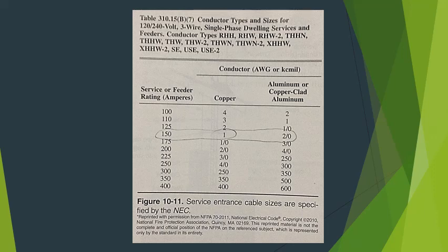Whether conduit or cable is used will depend upon the customer preference, local codes, building structure, environment, utility specifications, and the electrician's experience. In either case, the conduit or cable must be securely fastened to the building with the proper clamps or supports as shown later in this chapter.